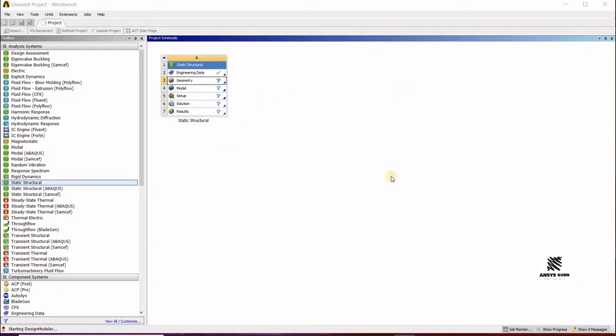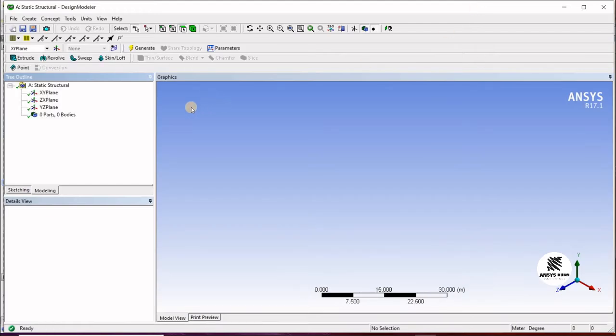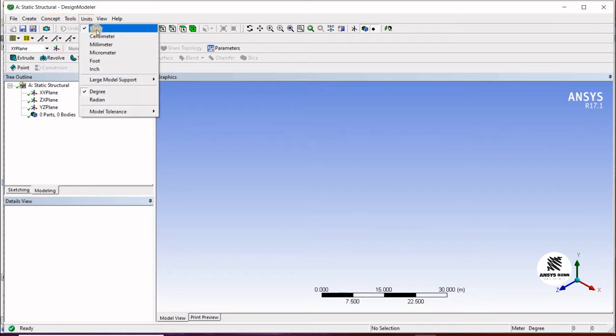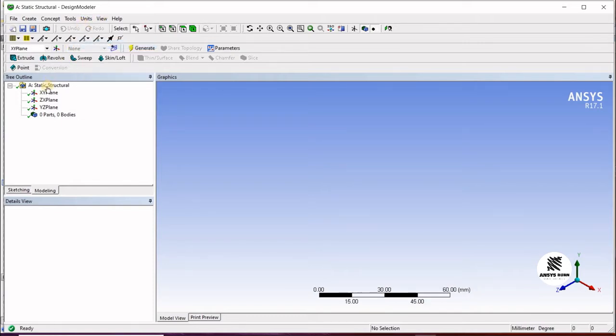It's just going to take a while. Once it pops up and we've created our model, we can go to the model. In this category we're going to assign the boundary conditions such as stress, fixed supports, and so on. Okay, let's open it up. Here the most important thing is to check the units. Initially it comes up with meter, centimeter, and so on. So let's select millimeter.